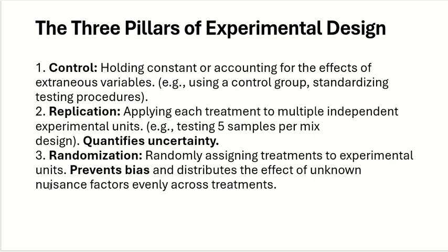Randomization is that you take the bias out of it. For example, if you say that I will first cast the beams without the admixture, and then I will cast the beams with the admixture, the ones without the admixture are all cast in one go, and then you will test them before the other set.